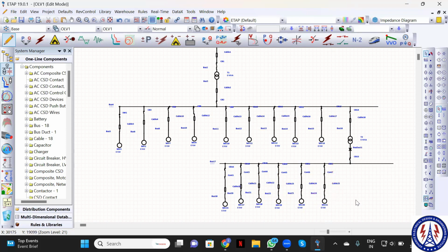Now create one more. After this, just add some power feeder. Motor feeders are enough. Now select the breaker and then lump load. I will tell you what is lump load then. Like this, add two loads. Breaker, then lump load. Breaker after the lump load. Just 1 minute, let me share something.